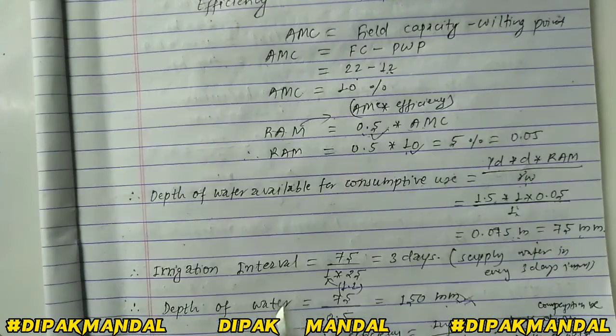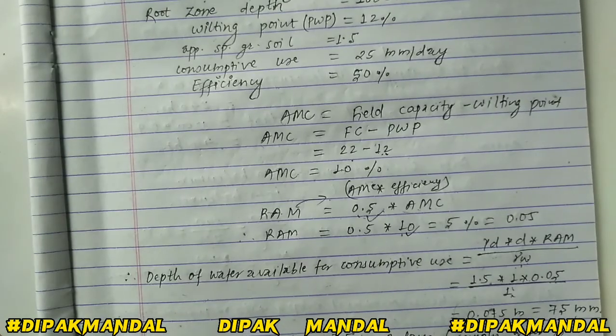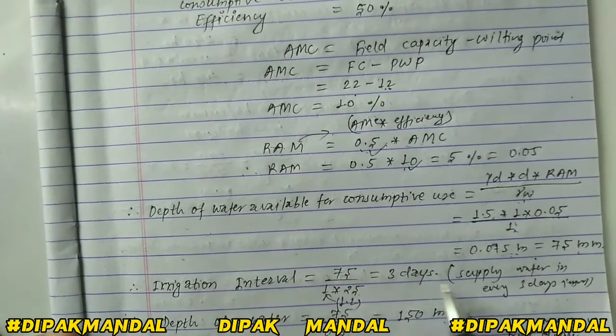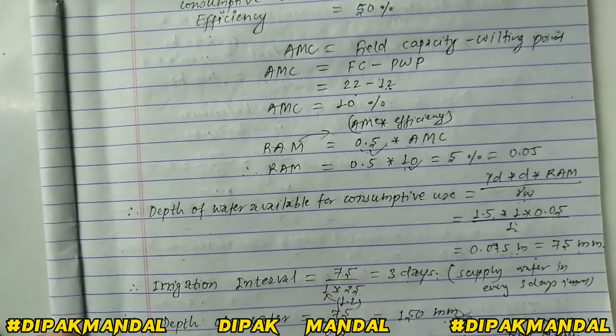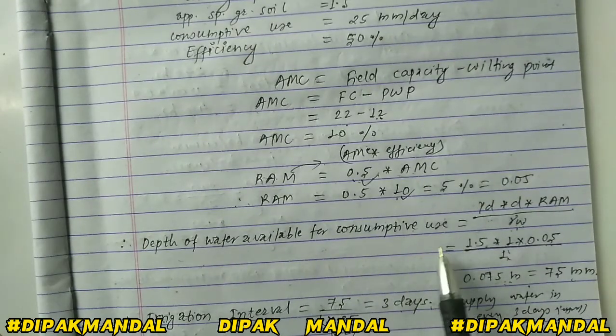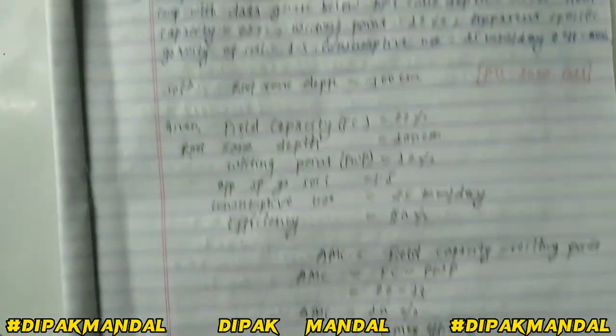So we have calculated the depth of water equal to 150 mm, and we have efficiency equal to 50%. At last we get the value of irrigation interval equal to 3 days, depth of water equal to 150 mm, and depth of water for the consumptive use becomes 75 mm. Okay, so that's all for this numerical.